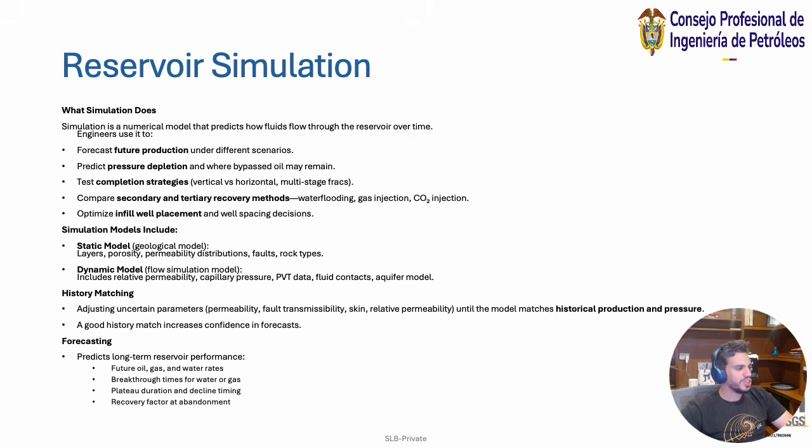They test completion strategies, vertical versus horizontal or multi-stage fracs or hydraulic fracturing jobs. They compare secondary and tertiary recovery methods like water flooding, gas injection, CO2 injection. They optimize infill well placement, like I had mentioned earlier, and well spacing decisions, right?